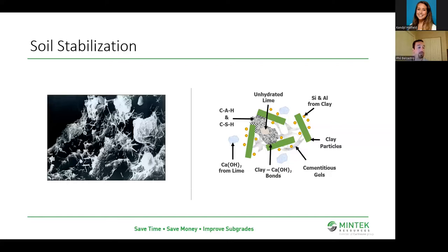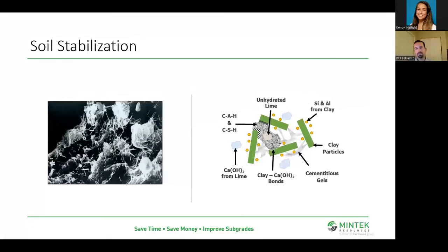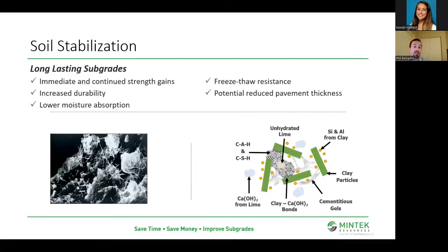So on the Calciment LKD side, we are supplementing those pozzolans. There might not be as much clay involved in those soils. So it's a great product that bridges the gap between those lime conducive soils and the cement conducive soils where it's more sandy. What that's going to do is help us form a solid monolith.